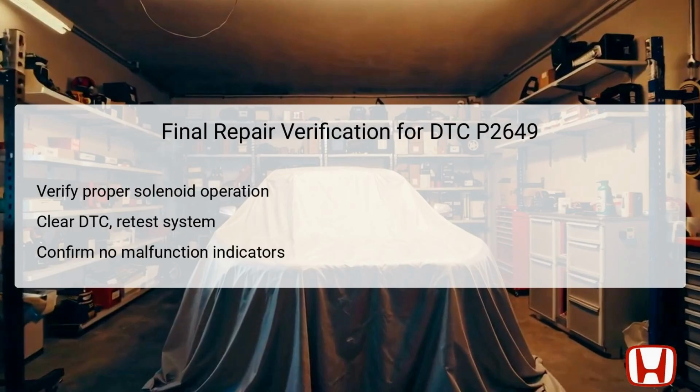Upon completing all troubleshooting steps for DTC P2649, it is crucial to verify that the rocker arm oil control solenoid is operating correctly. This can be done by reconnecting everything and monitoring performance after clearing the DTC with the HDS. Once cleared, retest the system under varying load conditions. The aim is to ensure no malfunction indicators reappear after testing, confirming that the repairs have been successful.